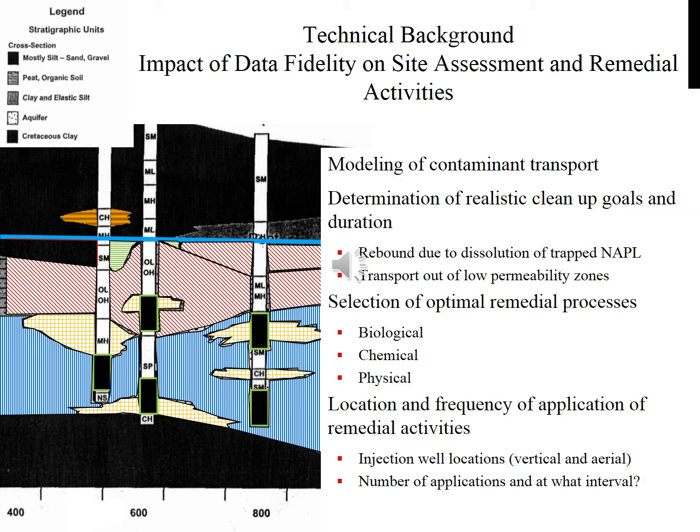So how would higher resolution data potentially impact the site assessment or remedial activities? Well, higher resolution data, particularly more accurate information, would allow you to better model contaminant transport, particularly with respect to low permeability zones, in which case wells often have difficulty returning accurate information. It could help determine realistic cleanup goals or duration of cleanup, allow you to better predict if there's going to be rebound due to dissolution of trapped DNAPL,